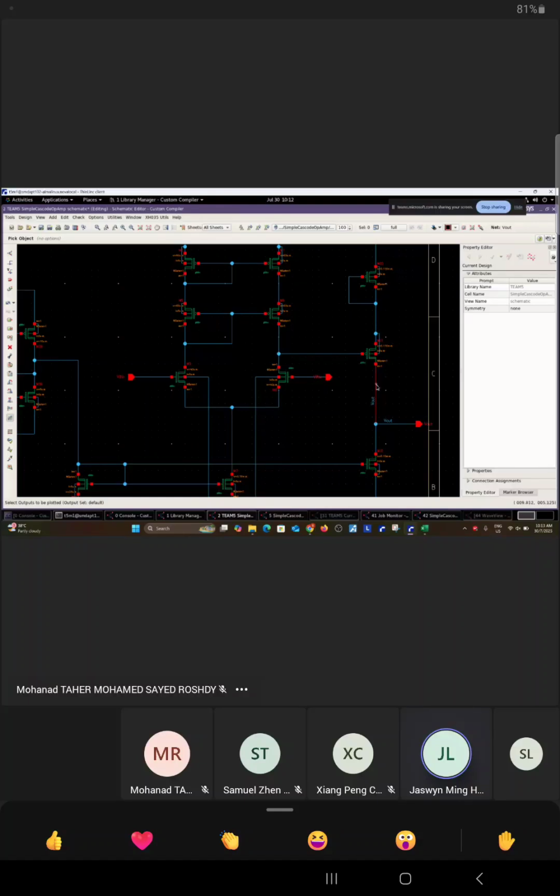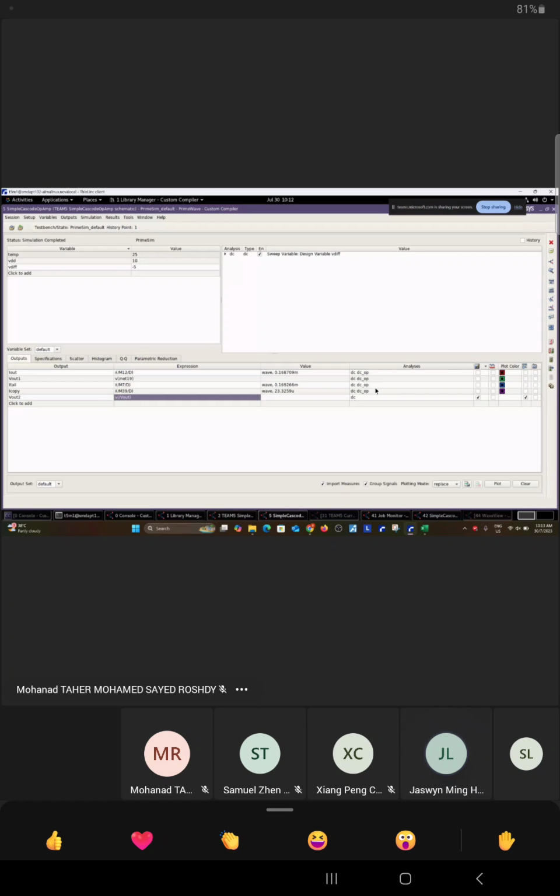I think if you click the line, this means it is a current, is it? Oh, this is a voltage. If you want to click on current, you have to choose on the terminal, not the node. Okay, the other way around. Click here. So right now you have 4 of these. Then we're going to do a DC sweep for these 4 values. So you can click on the waveform, for these 2, Vout1 and Vout2 here. Then you can run the simulation.